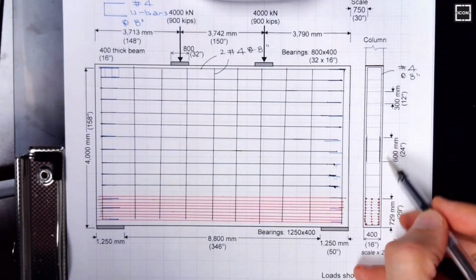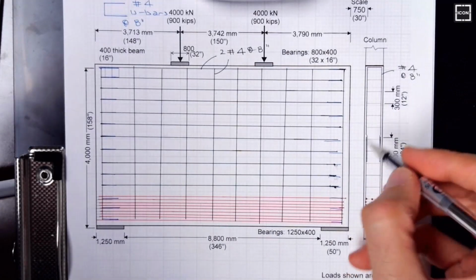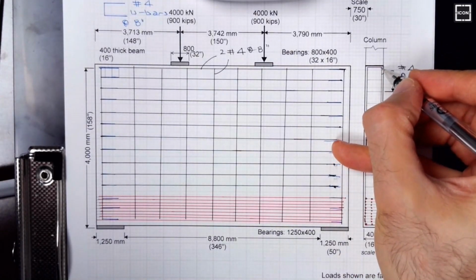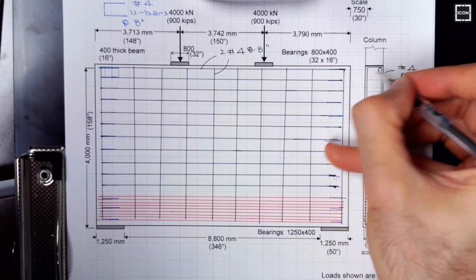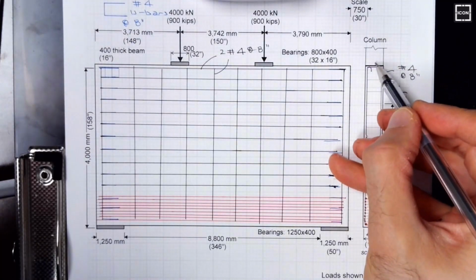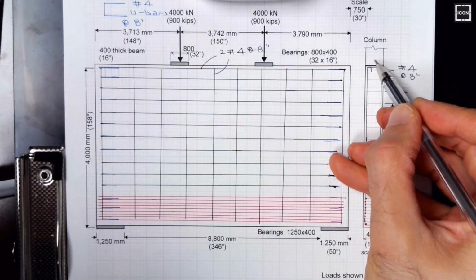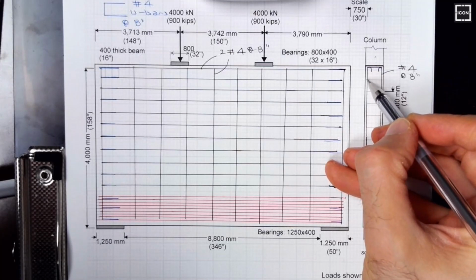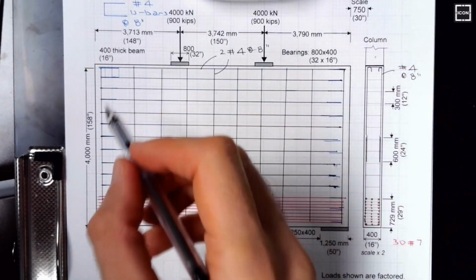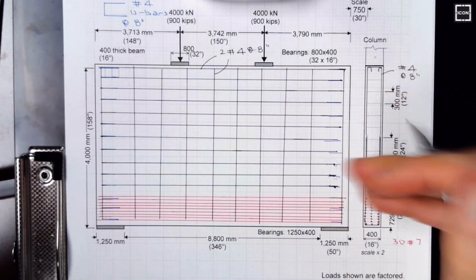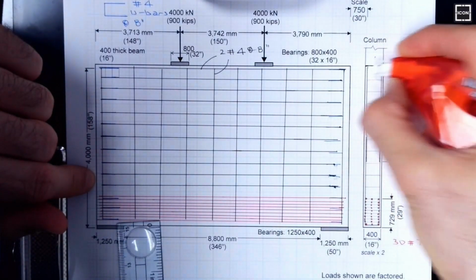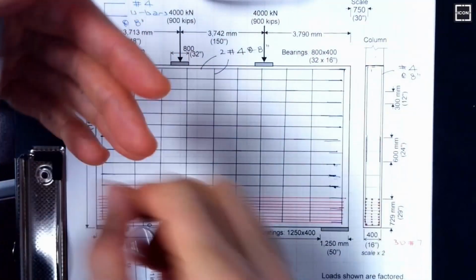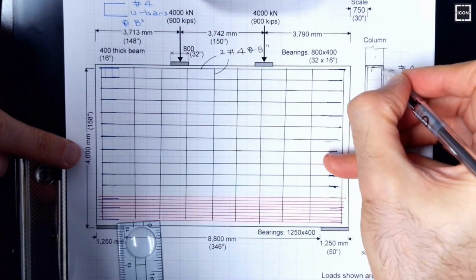Some overlap to provide continuity, but I mean, if you want to hook it, it's fine. The code allows you to hook it, so you can use straight bars. You can hook it this side, but then your member would not be confined, so you are applying significant compression. So again, the U-bar would be perfect. So this closed stirrup pretty much serving the same purpose. You have a U-bar which confines the section. So I would much prefer not going with a hook, but a solid U-bar for crack control.